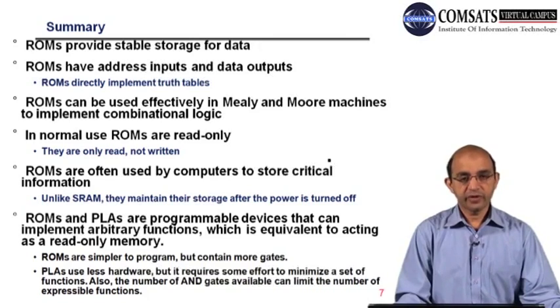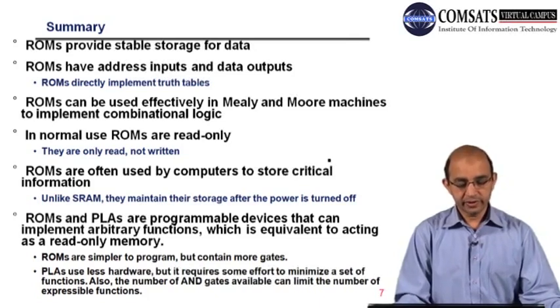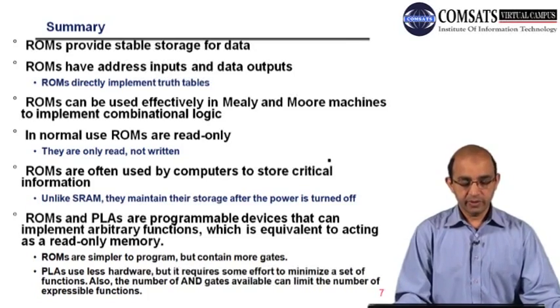But we have to be very, very careful, because if for example you are in the middle of updating your ROM, and by chance a power failure occurs, then it's very difficult to recover. So you have to do something else. You may have to do something that requires physical maintenance.